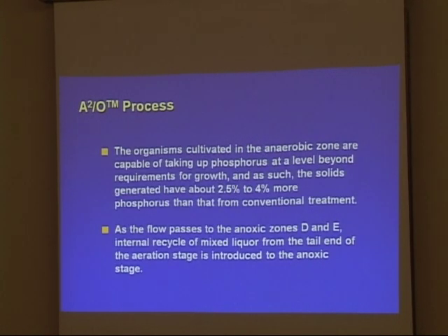Alright, the organisms cultivated in the anaerobic zone are capable of taking up phosphorus at a level beyond requirements for growth, as we've discussed before. As such, the solids generated have about 2.5 to 4% more phosphorus than from conventional treatment. They're basically stuffing themselves, the cows, the phosphorus absorbing organisms.